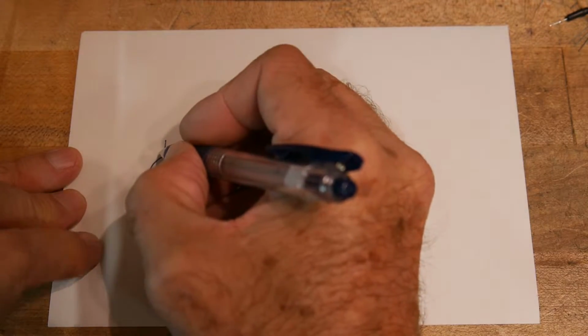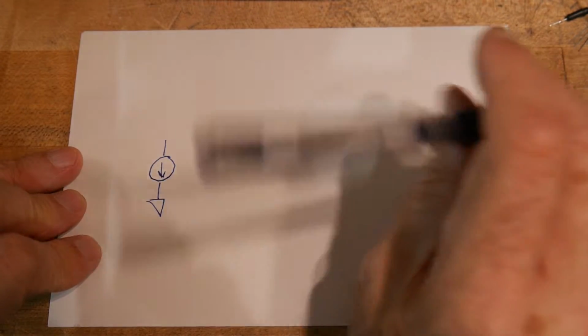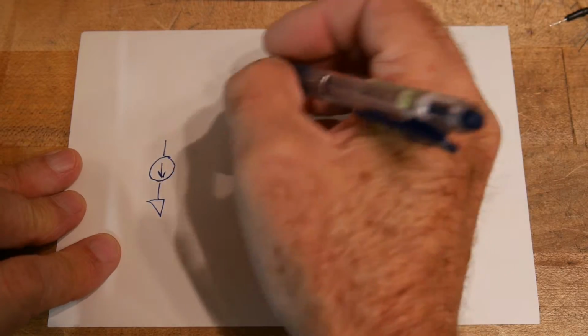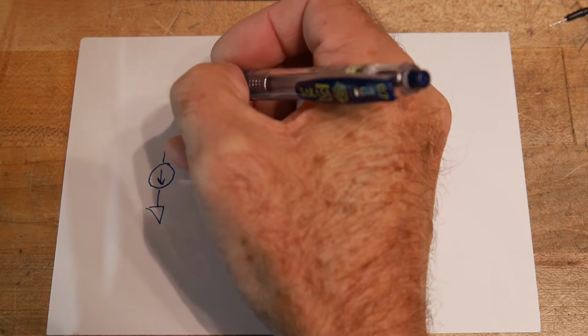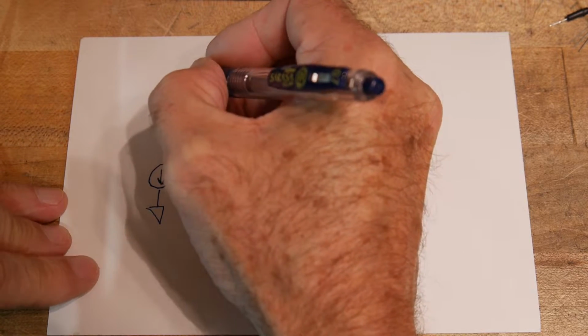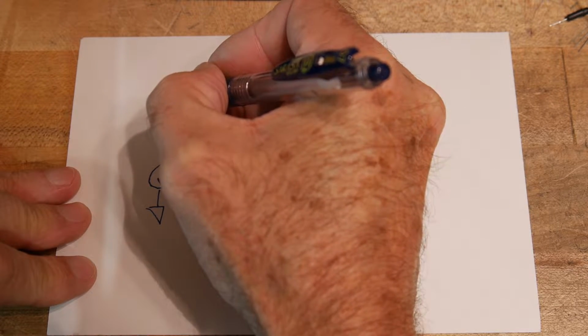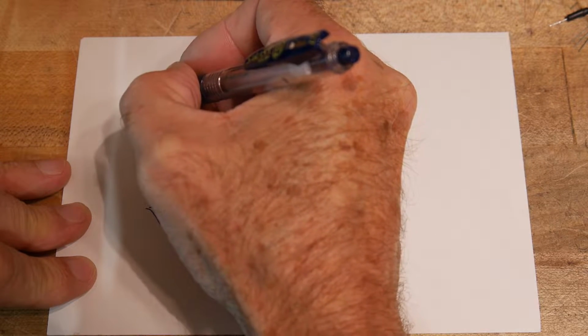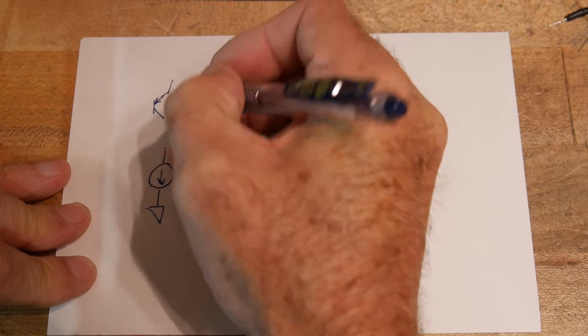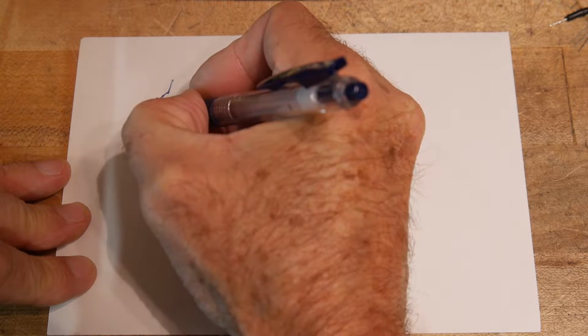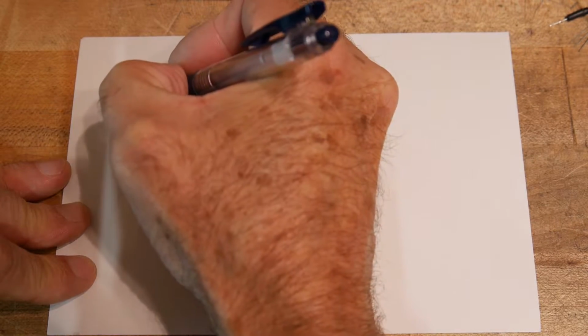And let's say that we want to have multiple current sources, right? And what we're going to do is we're going to use PNP transistors this time. We're going to have a PNP. And we're going to connect that PNP to this current source.